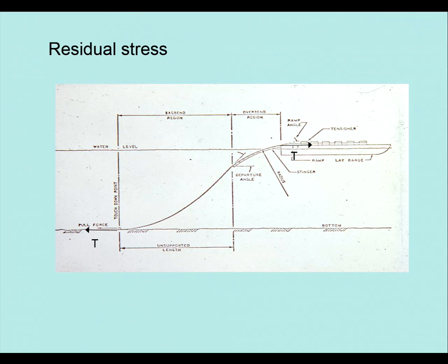And we take another beam, but the radius of that beam was controlled by this stinger, except when it came off the end there, then it would do that. And then what we'd do is find a point here where the properties of one beam were equal to the end properties of the other beam. And that was a point of contraflexure, and that enables us to work out the geometry. And that's how it used to be done.